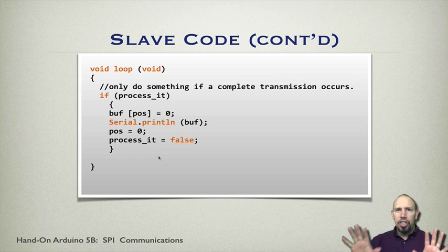So what's going to happen now is in this program, we load each of these codes into their separate processor. In this case, we're going to leave the USB connector connected to the slave, because we want to be able to have the serial monitor connected to that slave. We need that slave connected to our computer using the serial monitor, so we can actually read the console. And then we'll have the master just be on a 9-volt power supply.